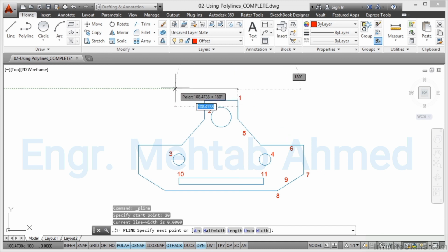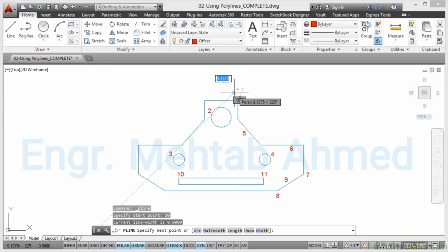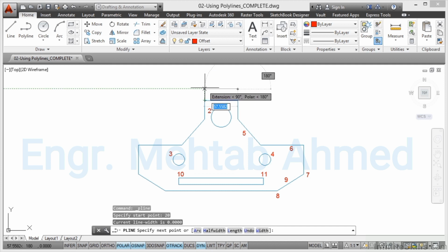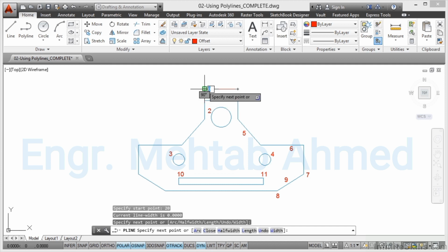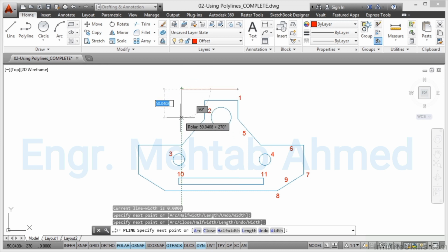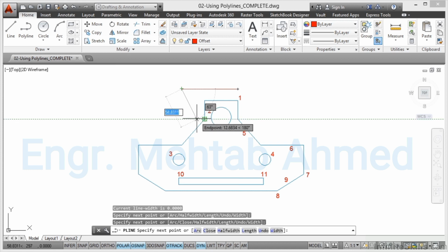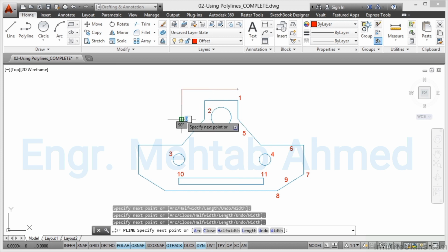And that line will start, can you see, as if it was the end point of the line we offset previously. I then hover over this point here and come up like so. Can you see I get an intersection because my object snap tracking's on? I click again. I then come out further, come down to this point here and hover, and then come up again until I get the intersection there. Click again, and then I come down again, hover over this point, drag outwards. When I get the intersection, I click there like so. I can then press enter if I want to close the Polyline command. But I could continue all the way around this shape if I wanted to.